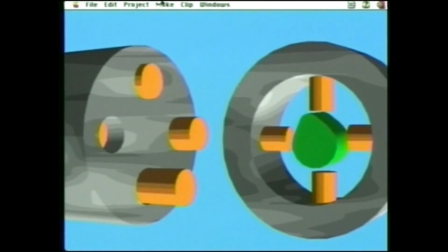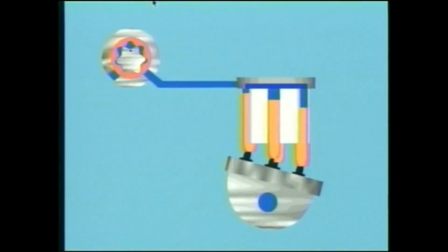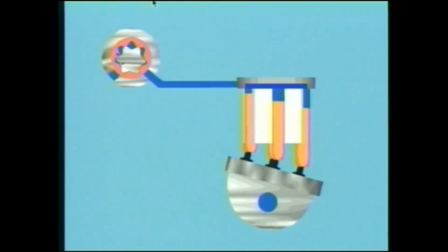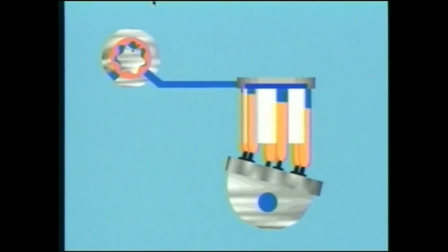There are two piston pump designs: axial piston pumps and radial piston pumps. The axial piston pump has cylinders that are lined parallel to the pump's driven shaft. Most piston pump circuits use a charge pump to pressurize the oil and force it into the piston pump.